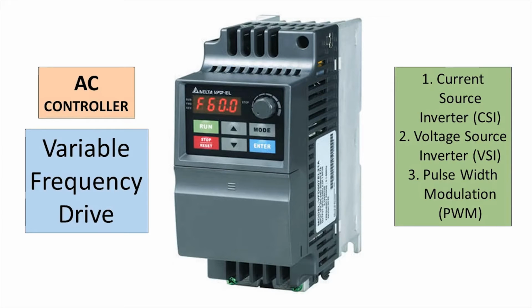Commonly used in various applications, a VFD can be found operating in ventilation systems, pumps, conveyors, and machine tool drives. The three main common VFD designs include current source inverter (CSI), voltage source inverter (VSI), and pulse width modulation (PWM).